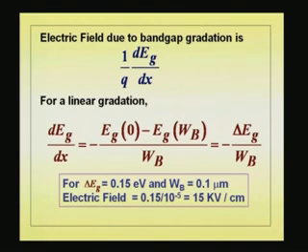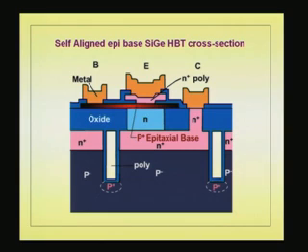Now, let us go further down into that. This is a structure that we can now run through with the results that people have reported. They have made devices which can go right up to 100 gigahertz. You go to the website and search for silicon germanium HBT, and you will see IBM results put across. They have made BiCMOS, they have made ECL, all sorts of things with silicon germanium technology. So it is a big contender for gallium arsenide technology. This is the challenge thrown by silicon technologies towards gallium arsenide based HBT. But still your high electron mobility transistor stays there, there is no contender here.